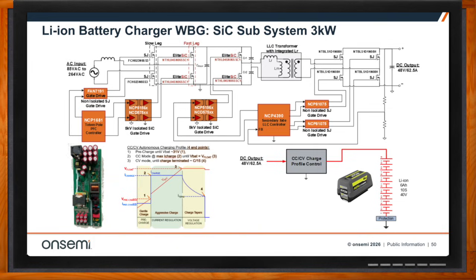That's called the CCCV charge profile control. And that follows the CCCV autonomous charging profile I have on the bottom left with the 4 endpoints. That's how you properly charge, one way to properly charge lithium ion. And now back to the block diagram.